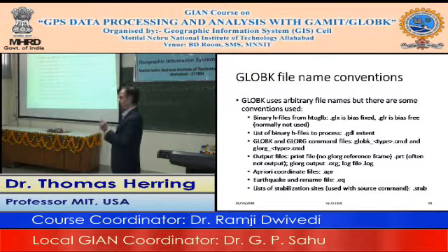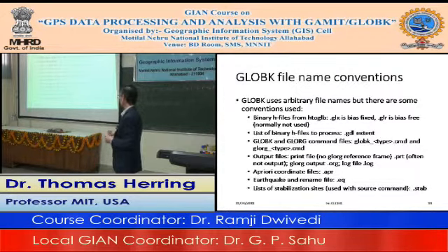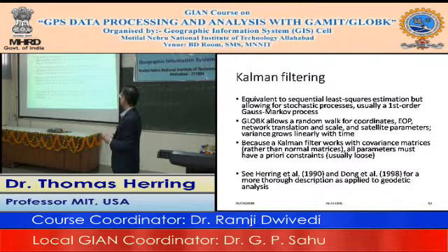We have a set of files which allow us to specify when earthquakes happen and any renames that we need, because we have misidentified a station or because we've changed an antenna and we want it to be treated as a separate site. Those we typically call a .eq file. And then the list of stabilization sites we want to use, we often end with .stab for stabilization. Again, you don't have to; that's what we tend to do. We'll come back and look at how those things interact with each other as we go across.